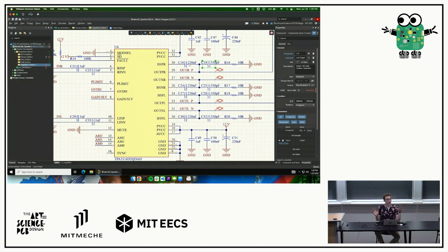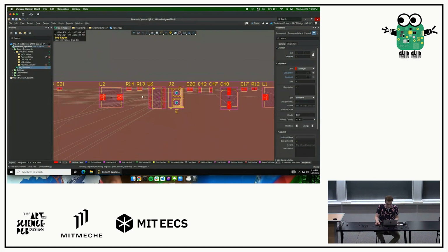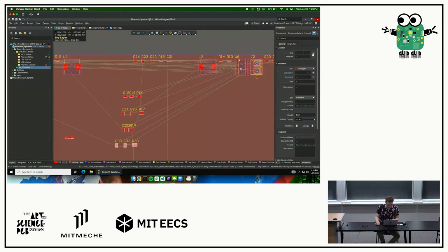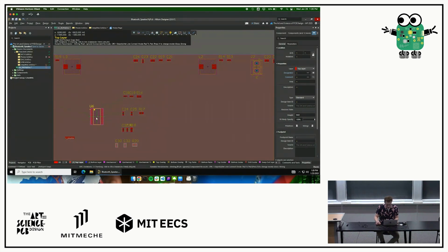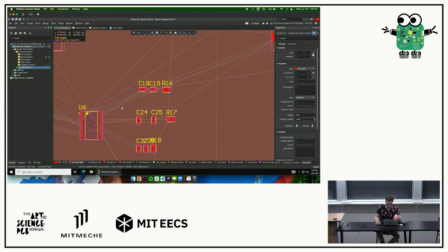Cool. Which side of the chip should it live on, now that we know this? Left side, right side? It should live on the right side, right? So what we'll do is take the chip, and let's just try and get the board layout to reflect that. Let's drag it over here, and then hey, look what happens. We have a lot more of our rat's nest pointing from these output pins over here to our little groups of 3 parts over here. Okay, great. We're starting to untangle this a little bit.